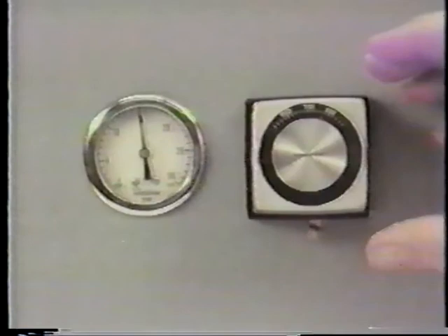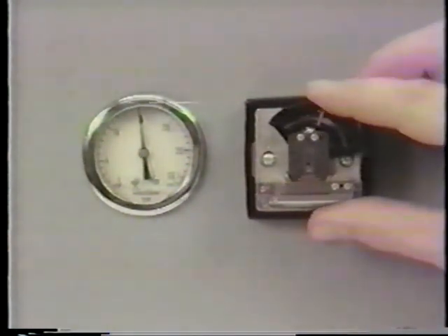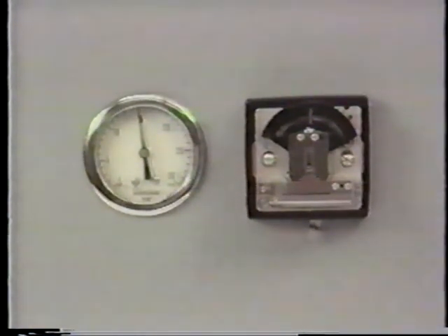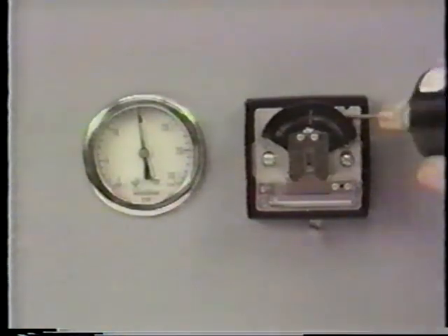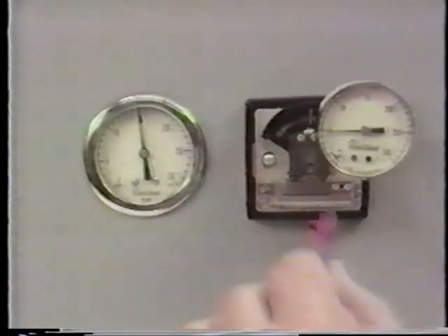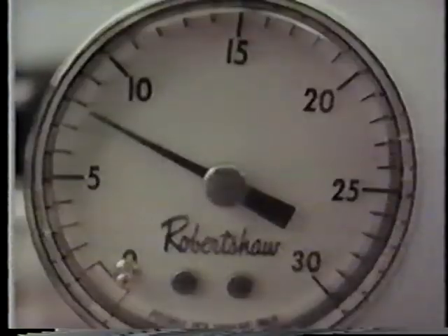To calibrate the day set point, position the day set point thumb wheel to match the ambient temperature. Set the main air supply pressure to 15 psig. Insert a branch tap adapter and gauge in the branch tap. Adjust the day calibration screw as necessary until the gauge reads 9 psig.